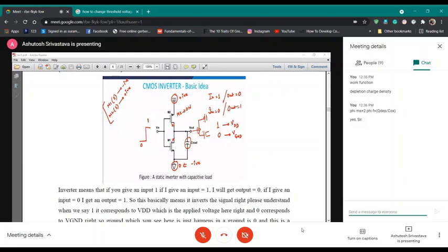Okay? Those were the parameters. I think you're not able to speak, but you have told all the parameters. Those parameters are related to doping concentration and other important parameters. You can change and control the threshold voltage by changing simple parameters like doping concentration or the work function. So when you're talking about work function difference, what does that mean?